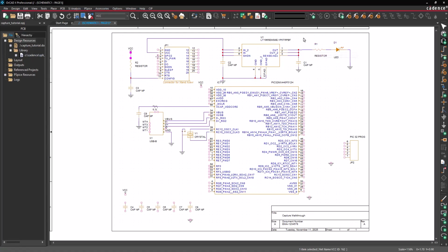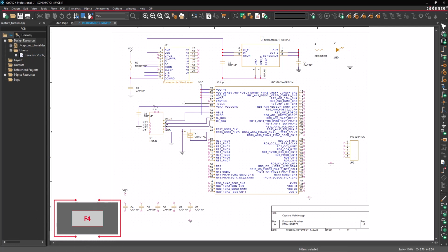On components JP1, JP2, and IC1, draw short wires to connect to buses and net aliases. To repeatedly place a wire, press F4 on the keyboard. Pins 4 and 5 of JP2 will be automatically connected to a bus, so do not add short wires to those pins.